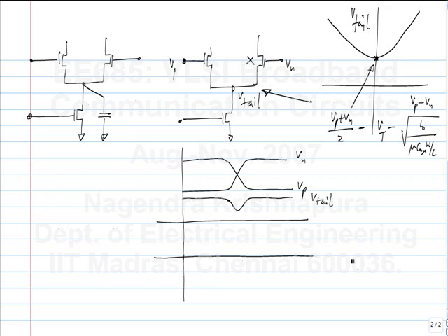So to make the analysis easy, what we'll do is we'll have a small capacitance. We'll connect a small capacitance to this node. Assume that the voltage waveform has not changed substantially, and see what happens to the current. Okay. So of course the transistor is still behaving like a current source of I0. What will be the current through IC? So it will be C times the derivative of this V tail. So it does something like this.